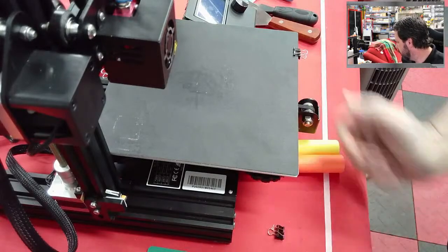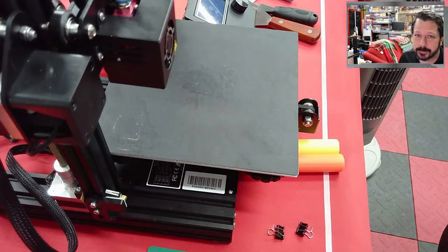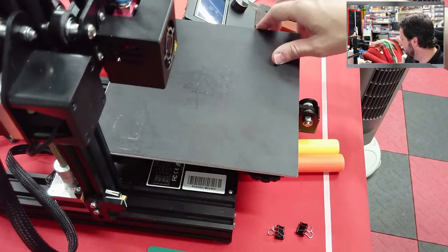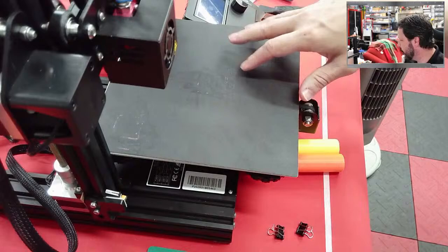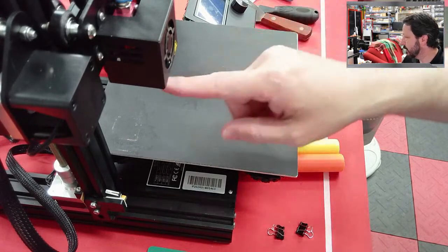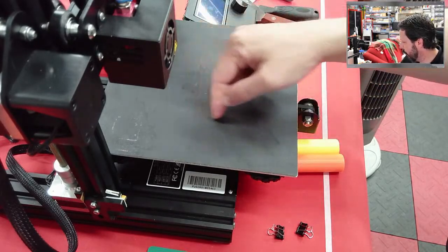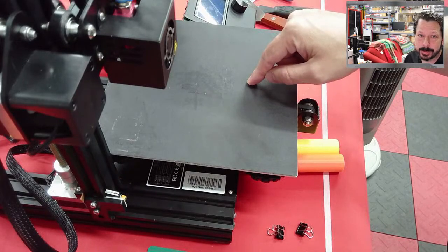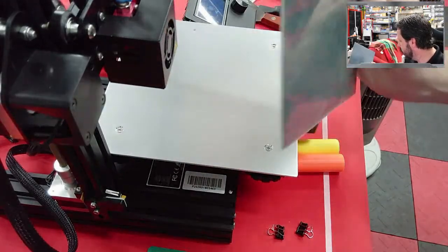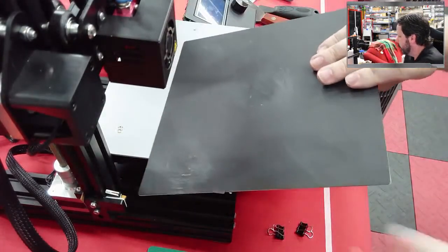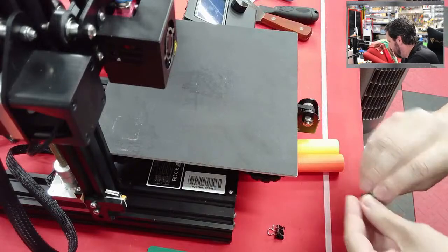So this one is not the magnetic kind. The magnetic kind that comes with these, the kind of floppy one, I always have trouble with those, because inevitably I will be trying to remove a part and I'll gouge that softer material. Or usually what happens is I don't get the nozzle the right height, and I draw basically lines into the bed, and it deforms it permanently with the hot nozzle, and it's got these little grooves in it. But this one's one of the rigid ones that's put on fiberglass, and so this one you can flex a little bit and pop parts off of it. So it's not a bad bed.